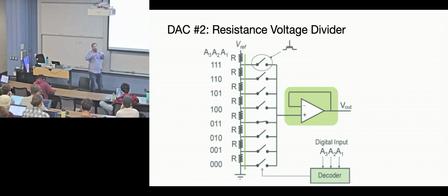That means the structures they make in silicon are all the same size and process variation should affect them all about the same, which gives you relatively good linearity. Then you just have a switching network that selects the one that you want. You probably have to have a buffer on the output, because from the reference voltage there's a lot of resistance in the path. So this would have a huge source resistance, and that's why you need that buffer.